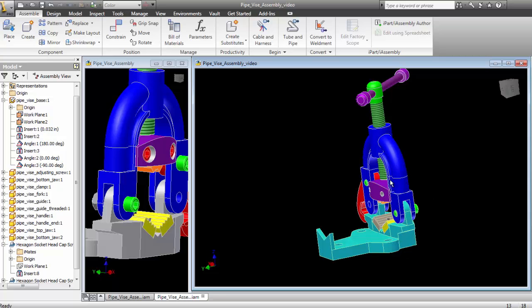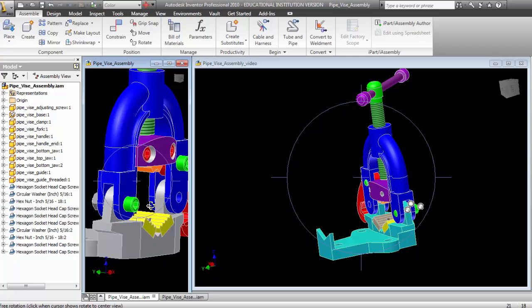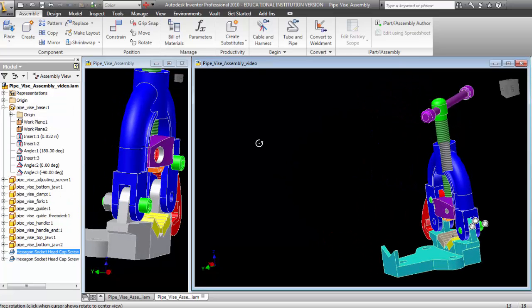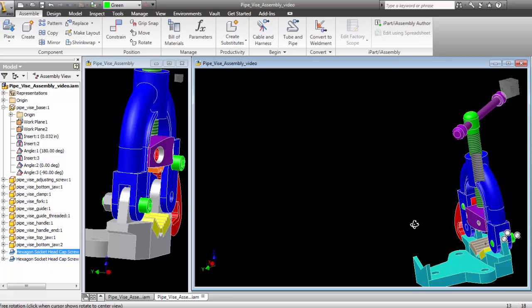With that being the case, we've got to do a little work. First thing I'm going to do is hit save. From there, I'm going to go in and go to these two and change them. Notice it says it's 5/16-18 and it's 7/8 long. I still don't really know how long I need to make that. Personally, I know I need 1 1/4 inches, but I don't have my nut and washer in there. So that might be a little bit of an issue.